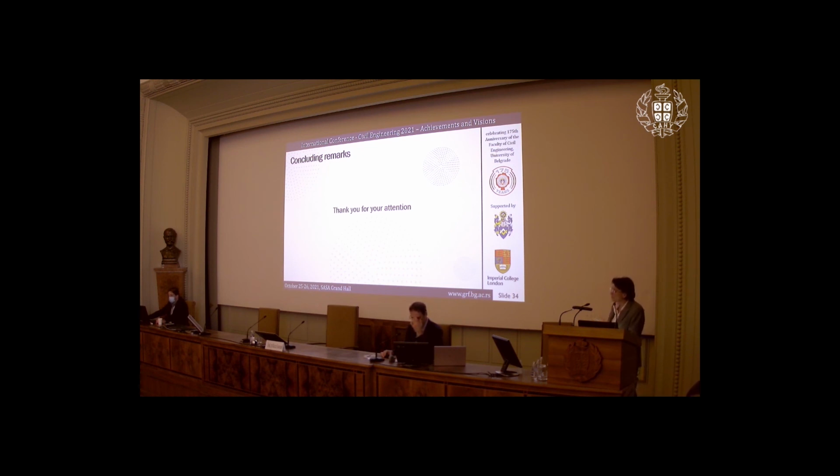There are some correlations that we can use to interpret the direct design parameters that we need, but using that immediately in design, I would not necessarily go forward without checking with localized sampling and testing in the laboratory as well. So my approach would be integrating both, not going one or the other, because they both have a value and they fill the information from one to the other where the gap exists.